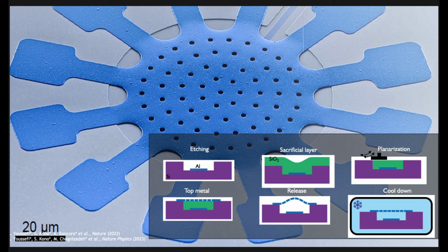And so I won't go into much detail, but evidently a lot in optomechanics depends on making systems that have exquisite mechanical and microwave properties. So this is our vacuum gap capacitor. It's made in a slightly different fashion, where we can very accurately control the gap between the lower and the upper mechanical plate that form the capacitor. They're separated here by typically about 100 nanometers, and their dimension here is about 50 micron.